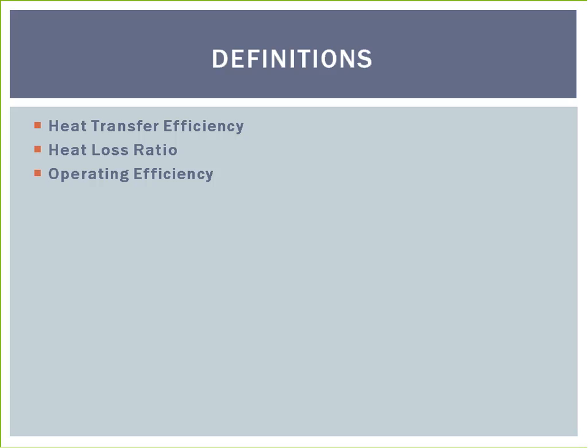Improvements can most often be made in regard to heat loss ratio efficiency by better insulating the boiler and piping systems. Heat loss ratio is also a value of the building envelope itself, and boilers have to react in relation to how a building loses heat. Improvements in heat loss for a facility should also be looked at when considering methods to improve efficiency. Improvements include better insulating the facility, improved glazing, and better control of airflow within and leaving the building.